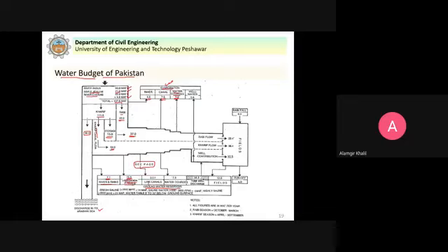From the link canals that link the two rivers, the seepage is estimated at 3 million acre feet. And from the water courses, another 7.5 million acre feet. From the groundwater, we are also supplementing the canal water irrigation system. So it says that 38.1 million acre feet of water is discharged through tube wells, the well contribution. And then it flows into the system. So there is again evaporation, well water, that is 5.6 million acre feet.